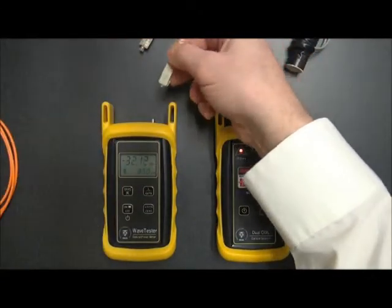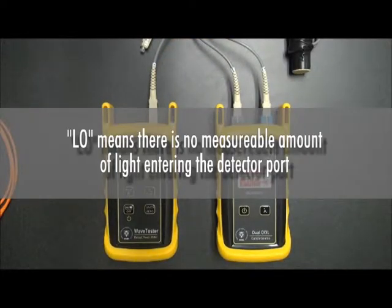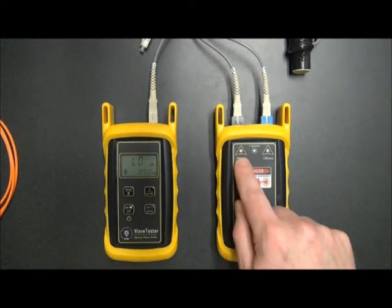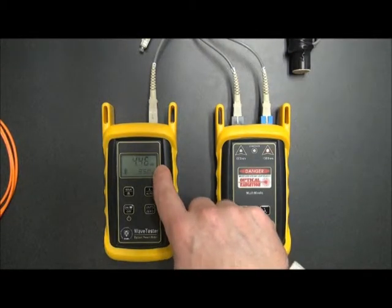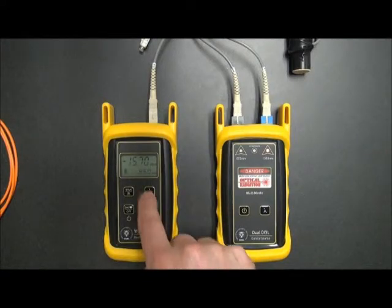Okay, so we connect in the 1300 wavelength, and you will notice that the reading is low. What low means is that there's no measurable amount of light coming into the photodetector. And as you may guess, the reason is that we haven't switched over to the 1300 wavelength yet. So we press the lambda button here to switch the wavelength over to 1300. And remember, we want to measure in dBm, but the meter is set to dB right now. So we use this units button until the meter is set to dBm. And we also need to switch the wavelength here because it says 850. We need to make sure it says 1300.